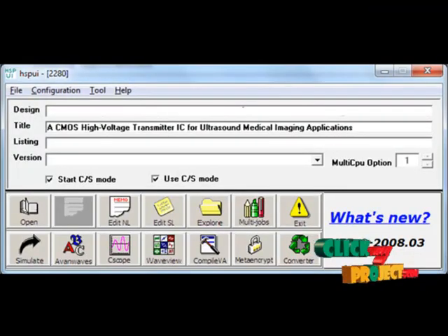Now I am going to explain the running procedure of our project. In the first stage, select the input file, cell0.sp file, then click the simulate option. This will simulate the internal structures, and finally it will provide the graphical representations for our output signal.